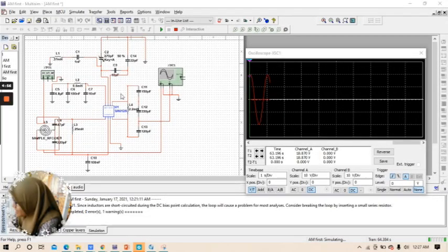Hi, so this is a design for the AM tank and auxiliary circuit. This is achieved by the use of the SA612A IC. This IC is a double balanced mixer and oscillator. The RF input in pins 1 and 2 is biased internally. They are symmetrical.